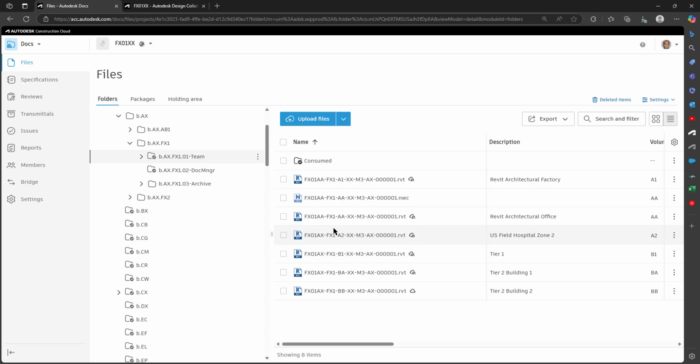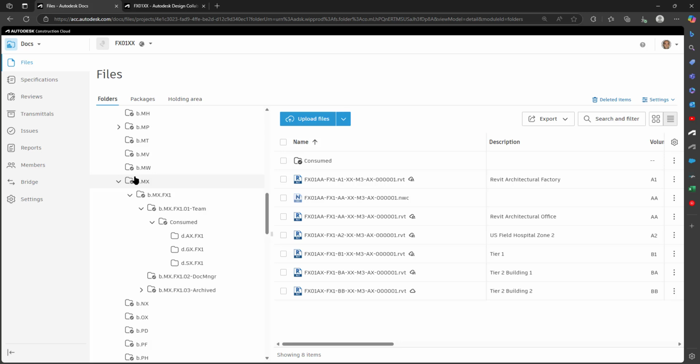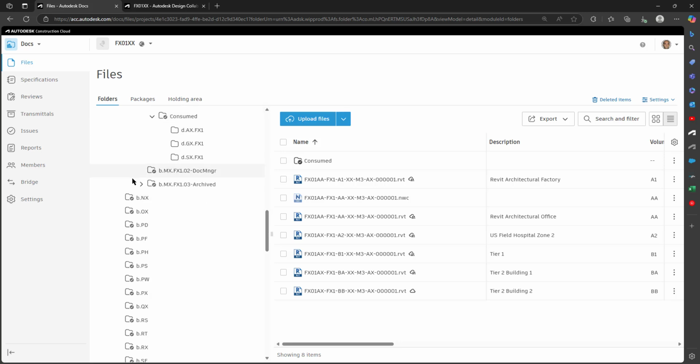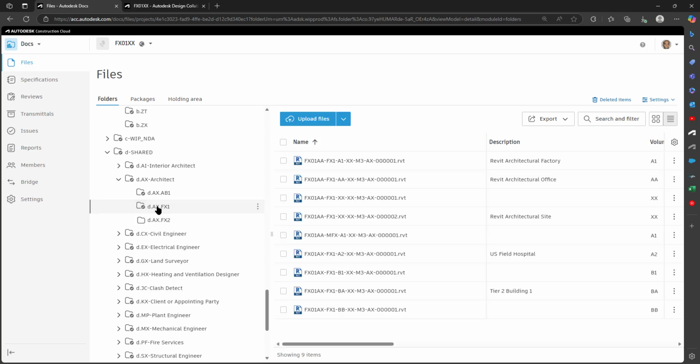Then to take your first tier models and repath the attached links to the files that are in the shared folder. And then to share the first tier link. So that would resolve all the problems that the other disciplines might have with your files in terms of the second tier links being linked into the first tier links when they link the files into their mechanical model.